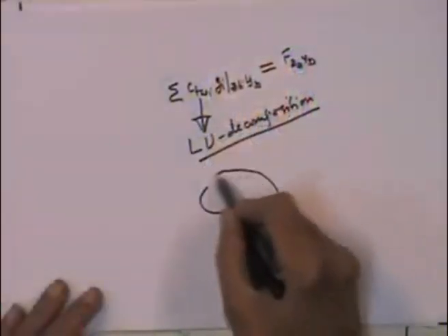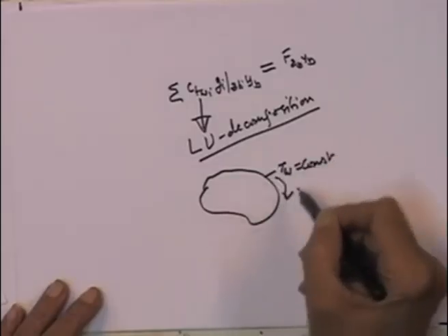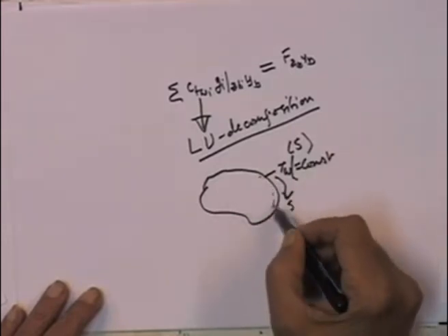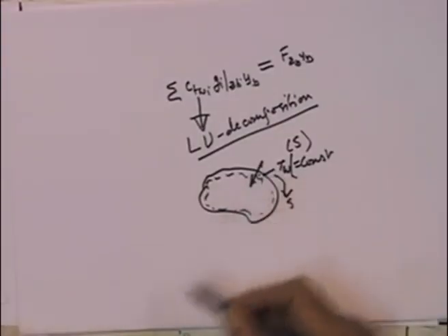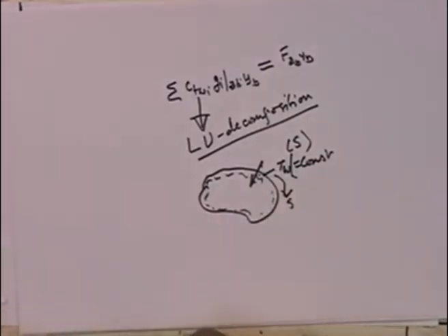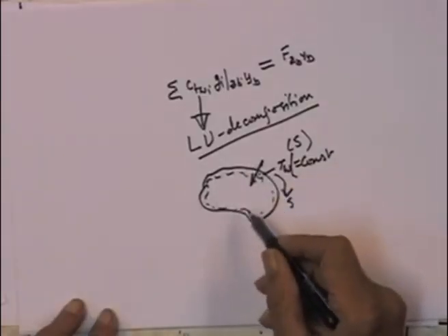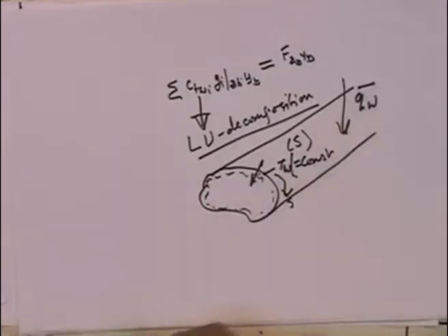Heat flux could vary along the periphery even when T w is constant, simply because, say I have a duct like this, even if T w was constant with respect to the periphery, the peripheral distance s, the velocity gradients and the temperature gradients can go on varying from point to point, and therefore, the local heat flux would be varying along the periphery, although its integral value would remain same as that specified, which is the constant heat flux q wall bar.